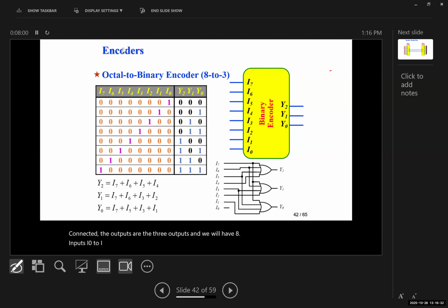And we can easily extract Y0, Y1, Y2 from this table, same as we did last time. We can create a K-map and find Y1, Y2, Y0, all of that from the K-map, and then find this function, and using that, be able to easily extract the circuit and write down the circuit and design the circuit and analyze it.